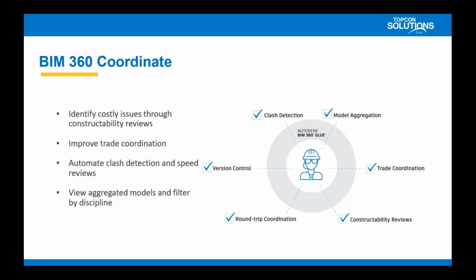Yep, I agree. And tying back to it, in the past, we've seen that typically this is hosted in Navisworks, but we're getting that siloed data approach where we receive a model every once in a while, and then it's our turn to aggregate all of those models and that data in Navisworks, run the model coordination, the clash detection, and then go through and create all of our reports. And each time you receive a new model, that's time to reach out to everyone else: do you have an updated model? Let's bring them all together.